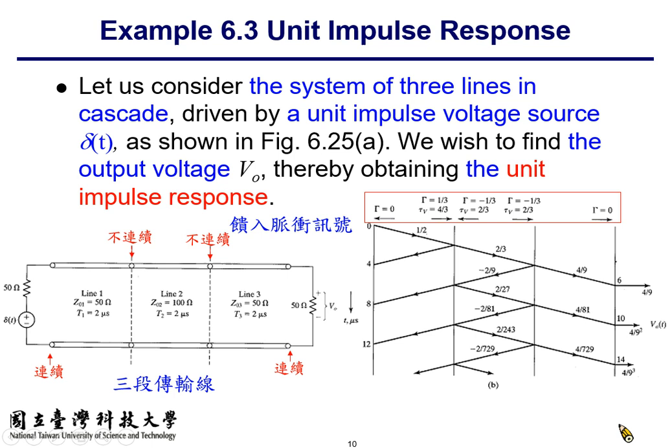And here you will experience some difference in characteristic impedance. So some of the energy goes forward and some is reflected back. And here it will experience a second discontinuity. So again, some of the energy goes forward and some is reflected back. And as you can see here, some of the energy reaches the far end, the right-hand side.